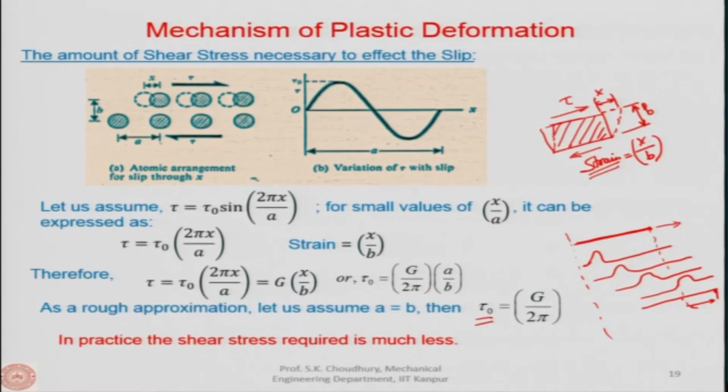As a matter of fact, we will see in one of the processes that when plastic deformation is made within a layer of almost perfect, that is ideal, material, the forces will be very high, and when forces are high, the power consumption for that process will be very high, because as I said, power is the product of force and velocity, F c and velocity V c.